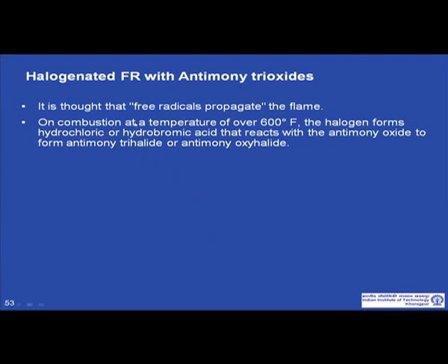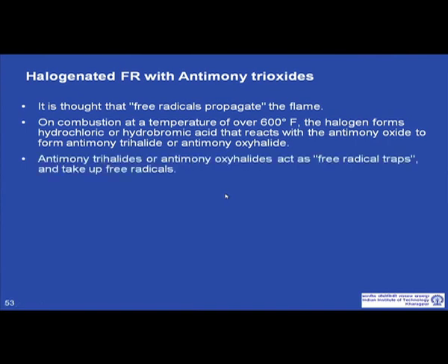On combustion at a temperature of about 600 degrees Fahrenheit, these halogens form hydrochloric or hydrobromic acids that react with the antimony oxides to form antimony halide or antimony oxyhalides, which trap those free radicals and prevent the chemical reactions.